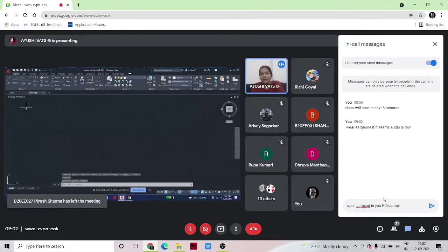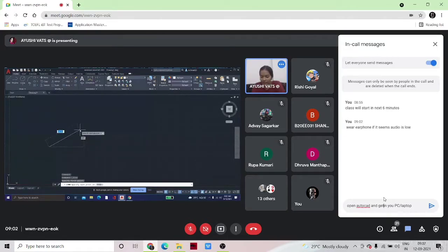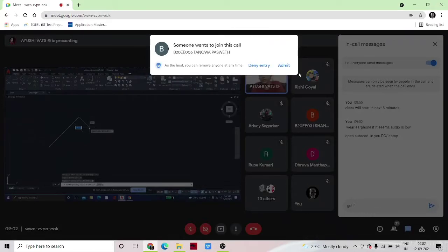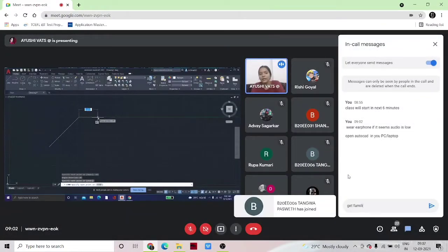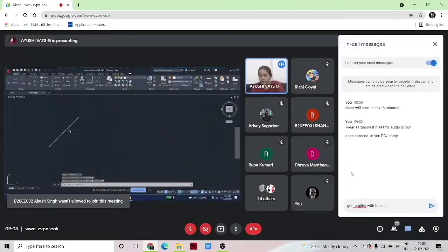If you want to draw a line at a fixed angle, then enter line command, specify the point and enter less than sign and the angle, like we have to draw an angle of 45 degree. 45. Enter. Our line is drawn at the angle of 45 degree. We can increase or decrease the length as our wish. See, this line is inclined at 45 degree. Now we can draw another line from that line. This line is inclined at 45 degree.